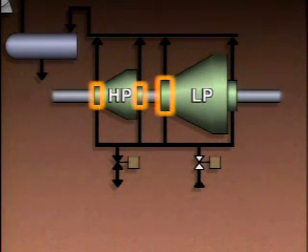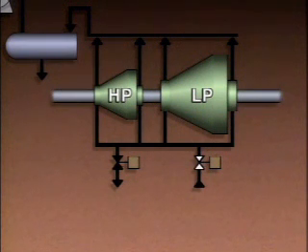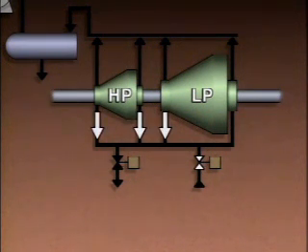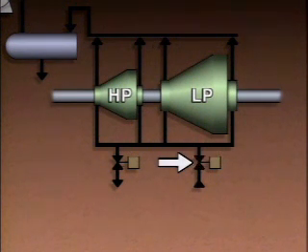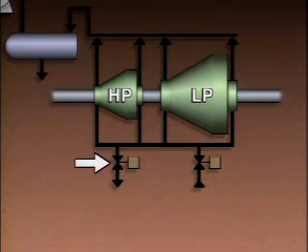Where the pressure is positive, steam must be prevented from leaking out. In this case, pressure in the gland is increased by steam leaking from the turbine. The steam supply valve closes because steam no longer needs to be supplied from outside the turbine. If the pressure increases to a certain point, the steam leak-off valve opens to prevent pressure from getting too high. Steam that passes through the leak-off valve is directed to a low-pressure area such as the main condenser.